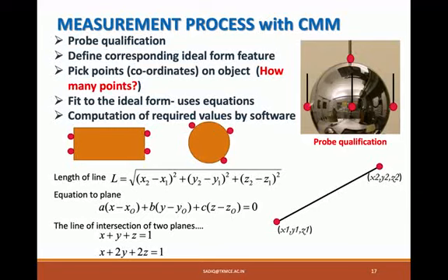Similarly, for all the touched points, the radial distance for the contact sphere will be taken by the system, and based on the computation and this data, the system will arrive at the value of the radius of the stylus tip, and the sphericity error in this tip. That information is further used by the system for arriving at the dimensions of workpieces. So probe qualification is the process of identifying the dimensions and form error of the probe that we are going to use for the measurement.